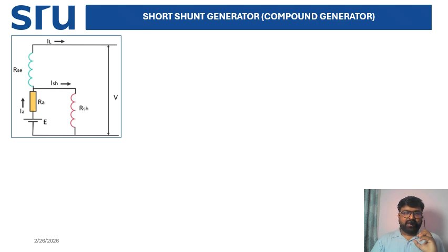And here, if it is difficult to distinguish, you mark this connection point as one, that is your A, suppose. Now the current IA is coming towards A. If you stand at a point, there are two directions: one is your shunt current direction, another is your series current direction, right? If these two currents are there, then if I stand at A, we know by KCL that the incoming current is equal to the outgoing current. You can write here at point A